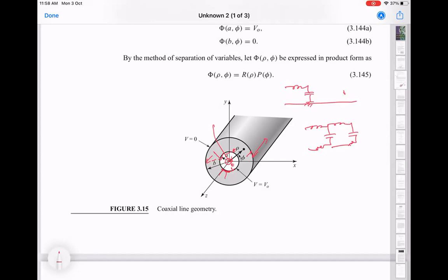Okay. So that makes it a natural way to define the outside ground. It's not just a matter of convenience, because what would you be looking for as you go from one point to another point in the transmission line is how the voltage is changing, right? If you just look at the ground surface, you're not going to see anything changing along the transmission line. Everything is going to happen on the center conductor with respect to the ground for the voltage. But for the currents, you're going to see changes in the center line.